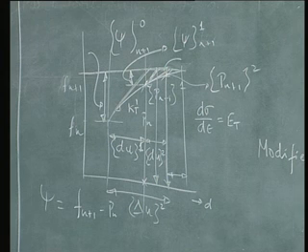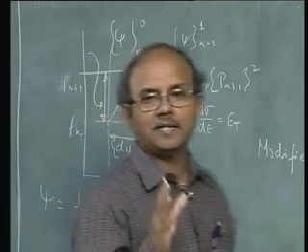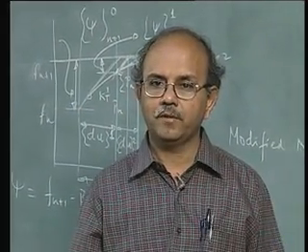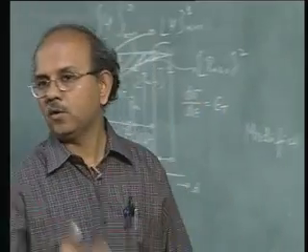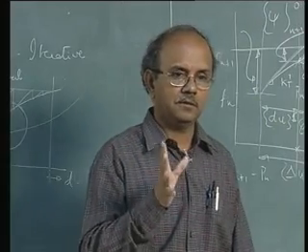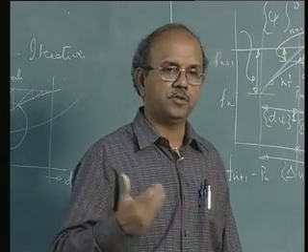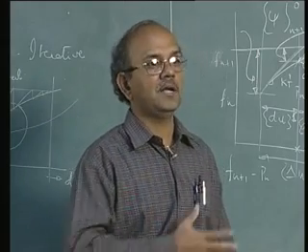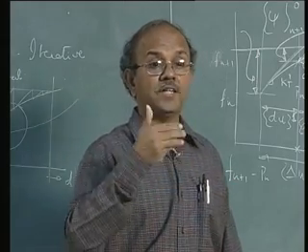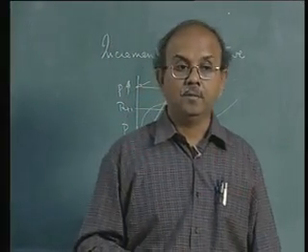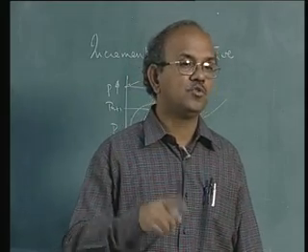But now, what is the advantage? No need to calculate. Yes, you need not calculate the tangent stiffness again and again. So, once you calculate it, you can, if you want to do whatever decomposition you want to do, you do that to solve the equations, keep it ready. So you need to keep substituting. So you have to calculate KT only once, and then decomposition you need to only do once, and so you can solve much faster or quickly when compared to the previous case. But the compromise is that you may have to go through a number of iterations.